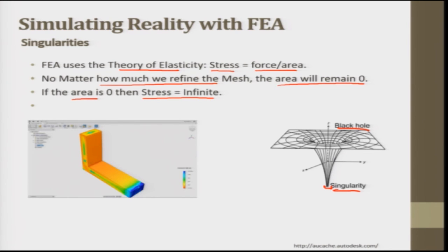Singularity can be confusing because it may cause an accuracy problem inside the model, which implies a problem with visualization, because singularity extends the range of stresses. So it has extended the range of stress here. This means that smaller stresses can appear to be negligible. Let me put a number. This is 1,000,000 units of stress. So this is only 2 units. So this looks to be negligible. This is why singularity is a problem here.